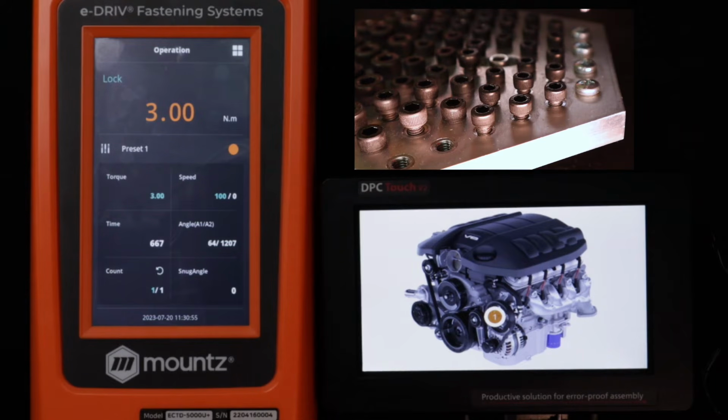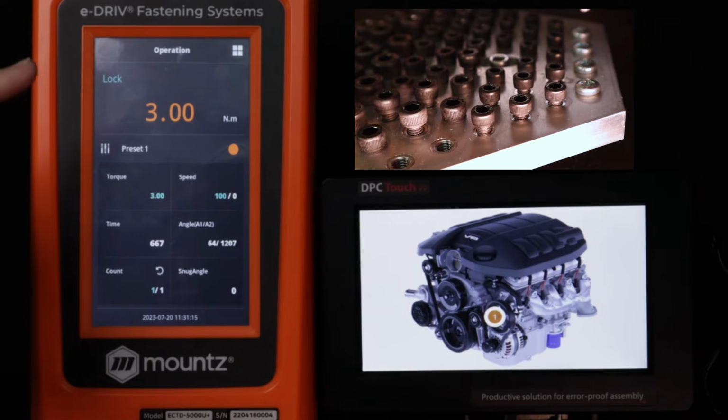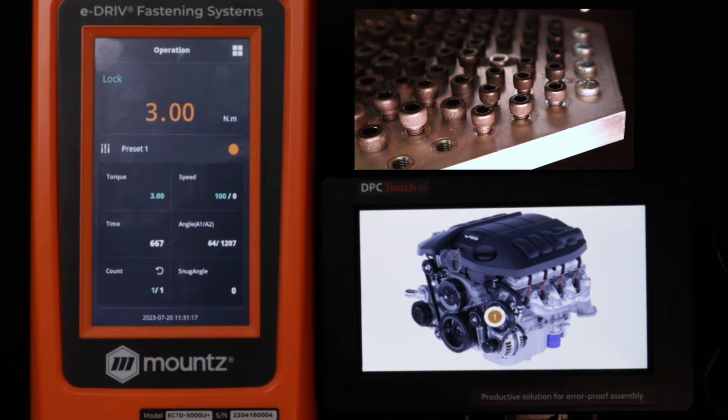This can help to simulate a flange type application or something that needs to be seated very, very precisely, so we don't get part of the assembly that is higher or that may cause a leak or those types of scenarios. In our preset, we have that set to just run an angle. We can have the system run to a specific torque value, or we can have it run to a specific angle.